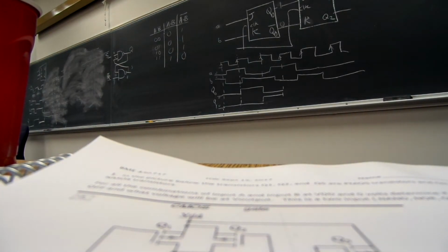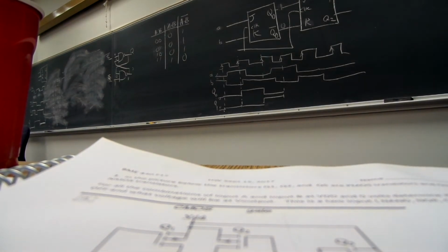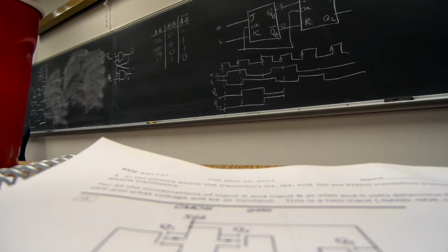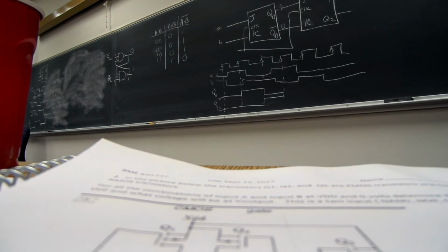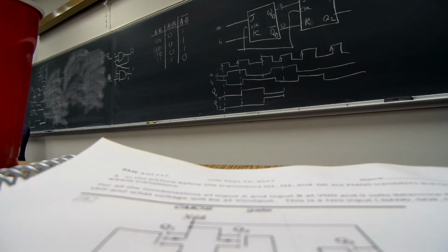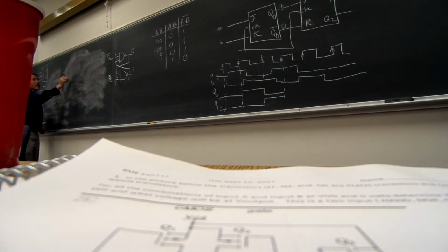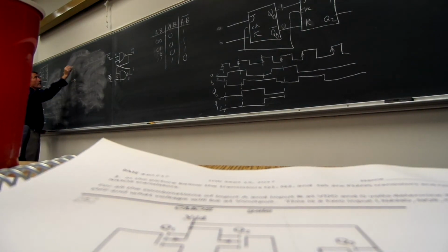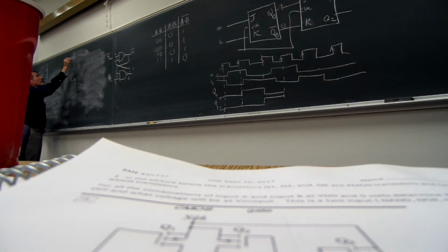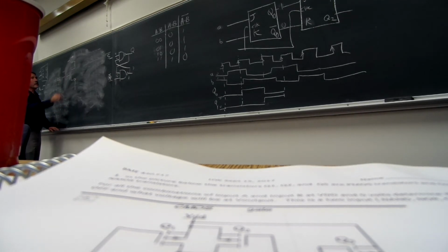PMOS. Source to gate voltage is a 1, it is on. And we model it as a 400 ohm resistor. Source to gate voltage 0, off. Model as an open circuit. Okay, once again, when you've got these gates like this, this is our invert gate.